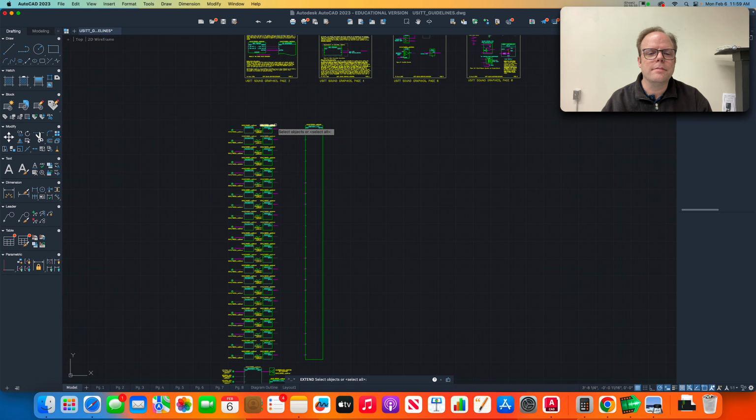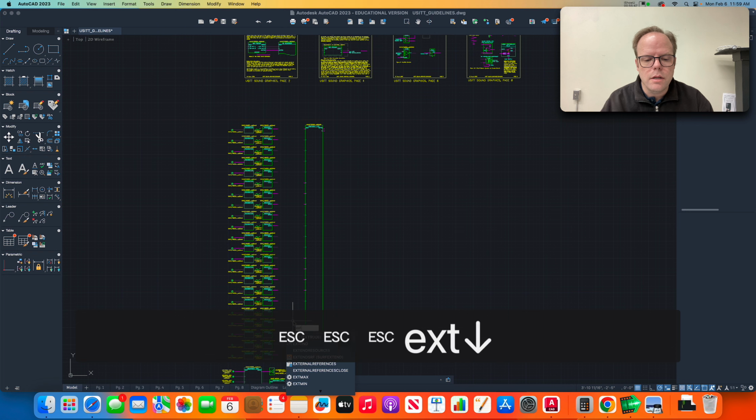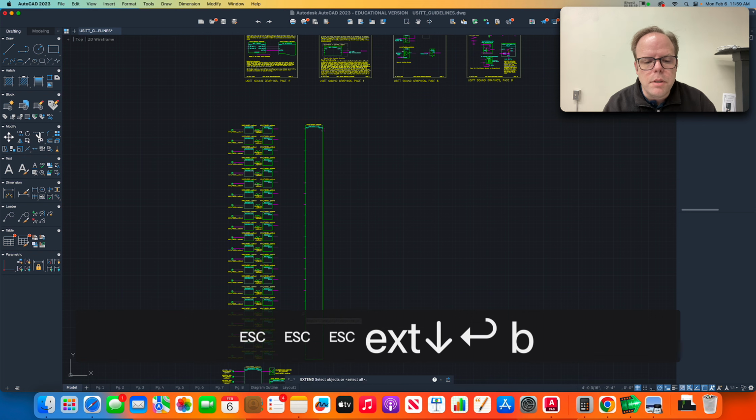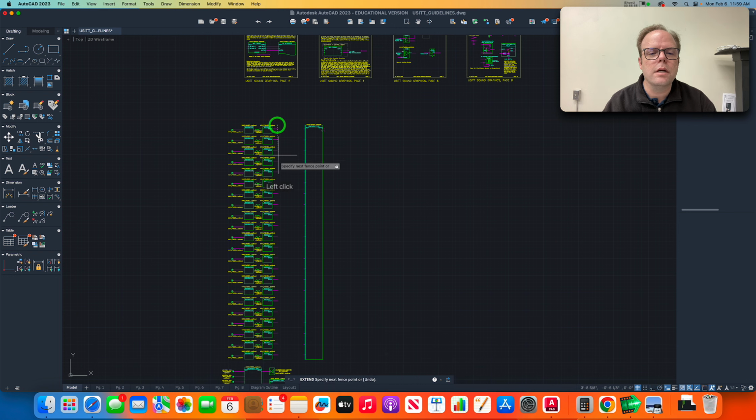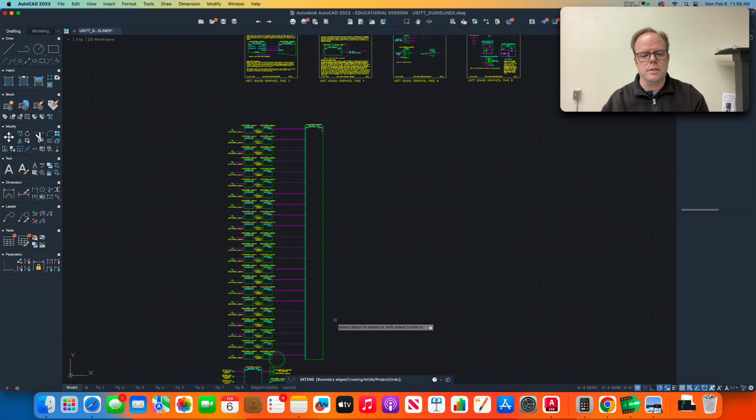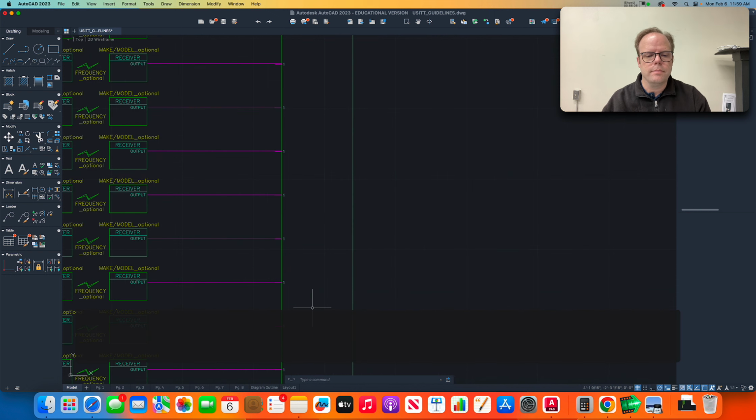It doesn't do a square. Oh, there it goes. Now I got it. Okay, so I can get it to do that, and I just select all those lines, and they all should extend if I do it right. Why am I struggling here? B for boundary edge. Object to extend. Oh yeah, I see it does just do a straight line. So I just draw a straight line down there, and as long as it crosses all those, it extends them all over there. There we go.